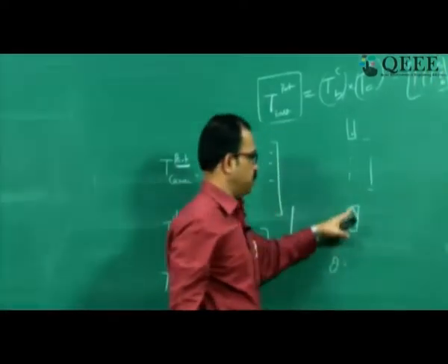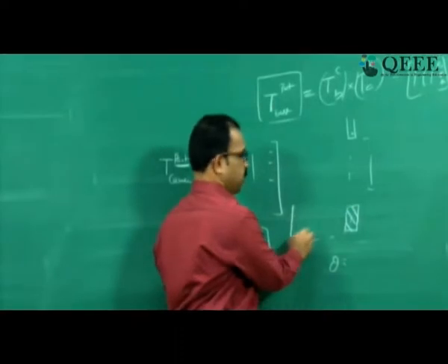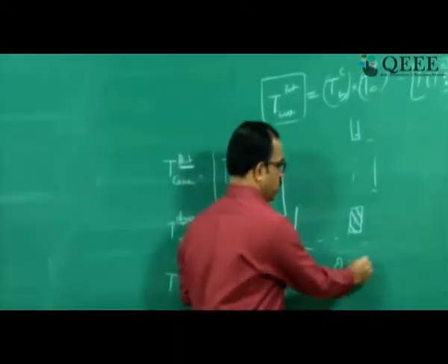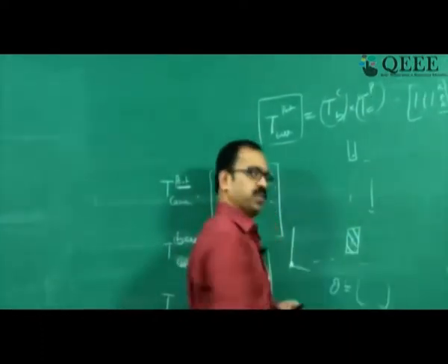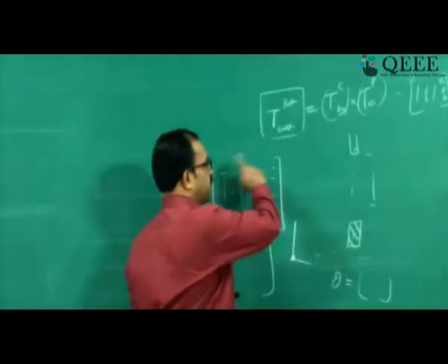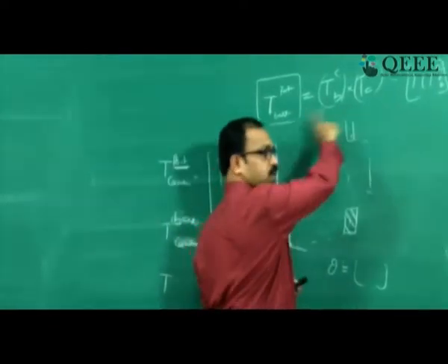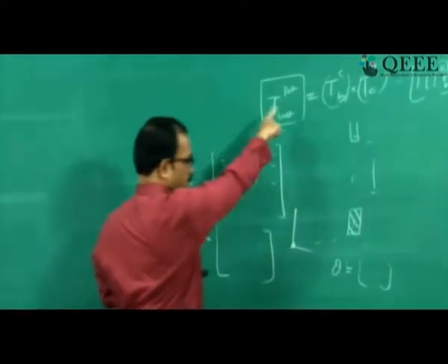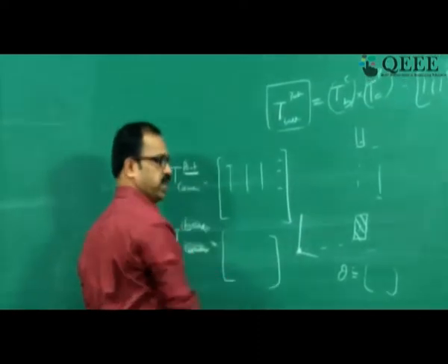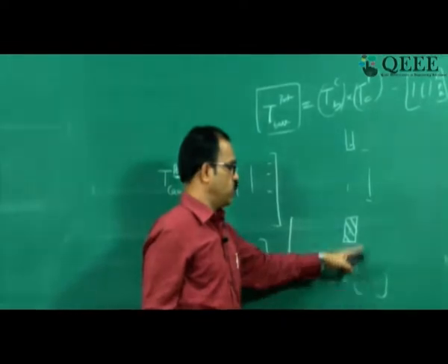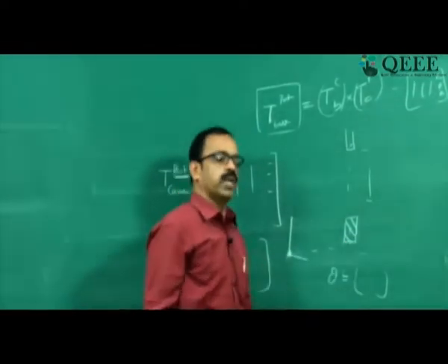Now it will do the inverse kinematics to find the joint angles to reach this position. Forward kinematics, through the transformation matrix, is used to get the position of the workpiece, and then we use inverse kinematics to solve for the joint angles to pick up this workpiece.